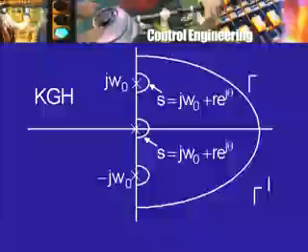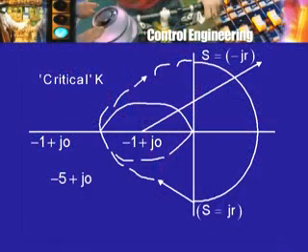The fourth will be, of course, the point of intersection of the image contour gamma prime with the negative real axis, because as we saw in our example, it is that point which turns out to be very critical, as shown here. What is happening here is usually of no concern to the encirclement, because the encirclement is at the point -1 plus j0. What is happening on this side, one has to be very careful. So, one will have to obtain the value of this point, the location of this point. Now, this requires some calculation. How does one do it?